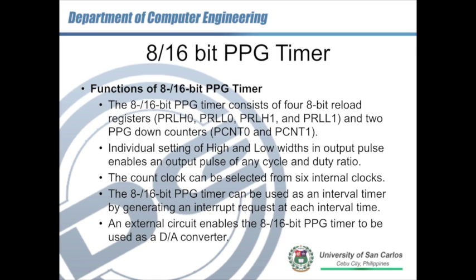So the functions of the 8-bit, 16-bit PPG timer consist of four. First, we have 8-bit reload registers. If you still remember our discussion about the reload timer, we had a reload register, and that was 16-bit. This time we have 8-bit reload registers. We have four.